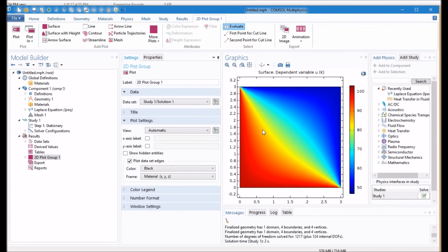Oh, wow, nice. So here are the results produced. It shows the temperature distribution in this square. And this color bar shows that blue is the low temperature and red is the high temperature. So you can compare this COMSOL figure with your pre-lab question figure that you produced from the MATLAB code. You compare them and see whether COMSOL gives you the right results, or whether you did it correctly. Alright, then we finished these pre-lab questions, and next we will do the LPCVD simulation.